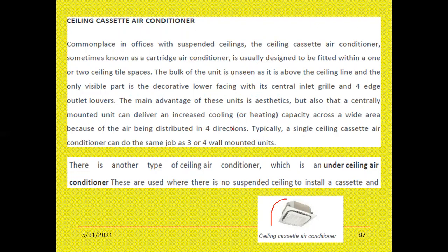The brine solution gets chilled and is pumped to the various air handling units installed at different floors of the building. The air handling units comprise the cooling coil through which the chilled brine flows, and the blower. The blower sucks the hot return air and blows it over the cooling coil. The cool air is then supplied to the space to be cooled through the ducts.